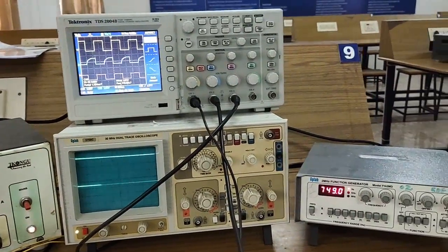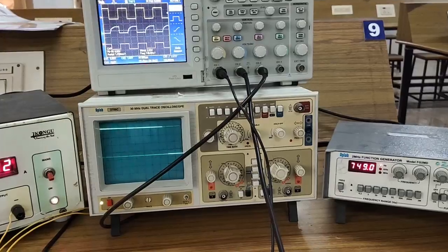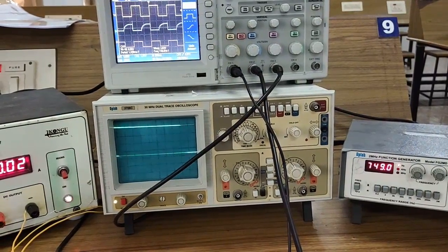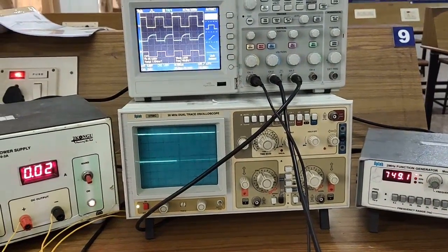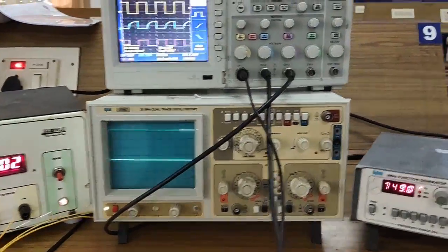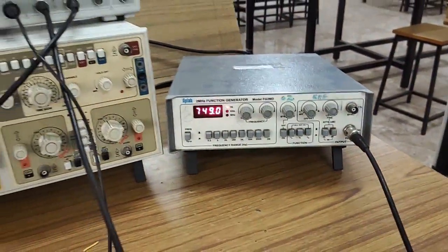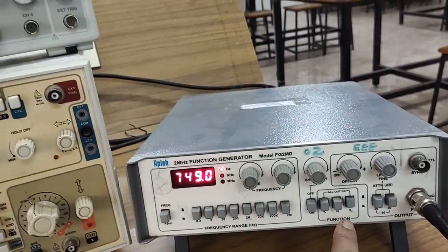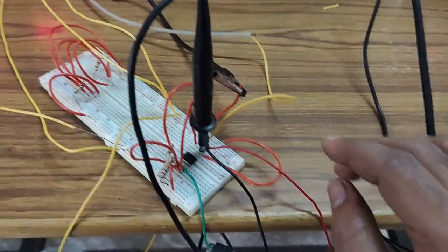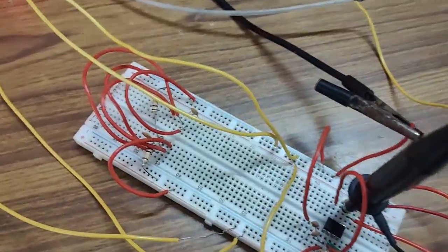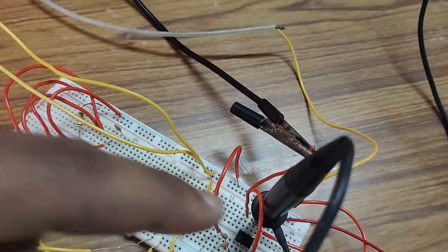So here we are going to measure 3 signals. One is to measure the input square wave, the other one is to measure the voltage across the capacitor, and the last one is your output at the 6th terminal, 6th pin of 555 timer IC. So here you can see one input is coming from here with a square wave as I mentioned earlier, and we have 2 outputs. One is across the capacitor, and the other one is at the output.